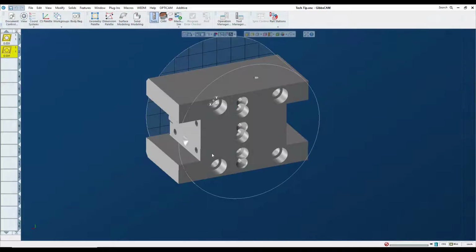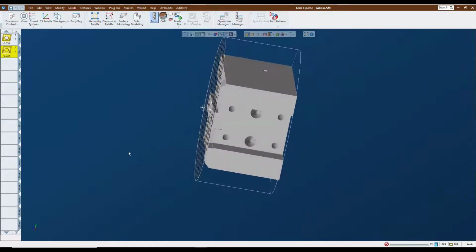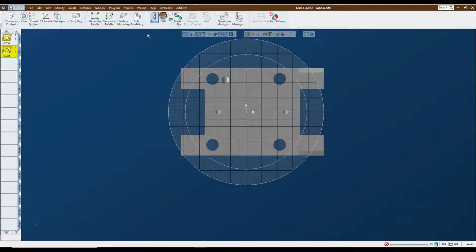And this is going to be a quick overview as to what is necessary in order to accomplish this. So we have our tool block here sitting in our view. We look at the XY coordinate system and we make sure that the tool block is positioned accurately to the center line of the turret. So we have our dimensions here and we see that we are positioned here accurately.